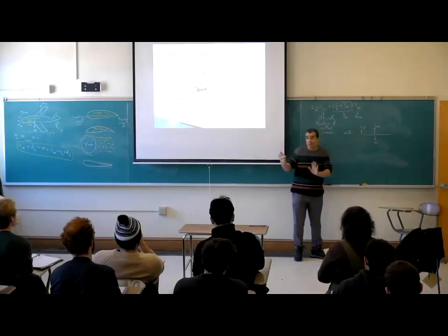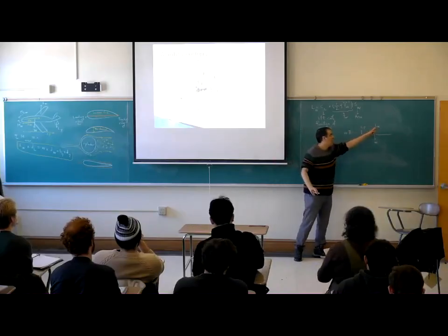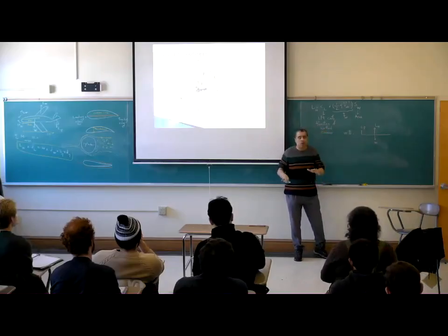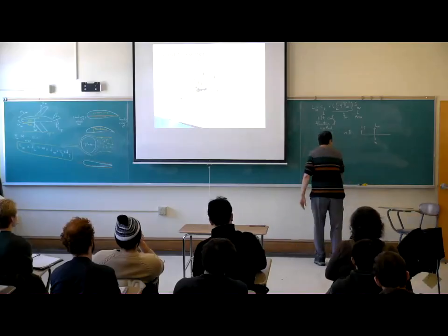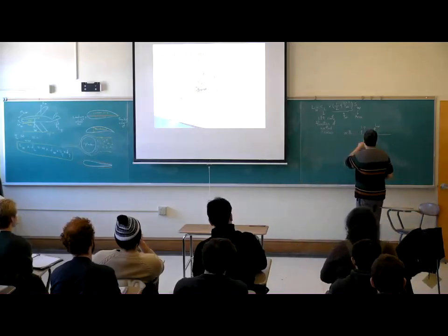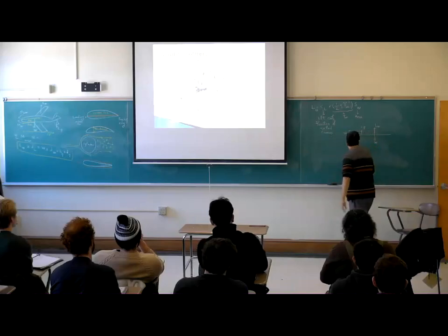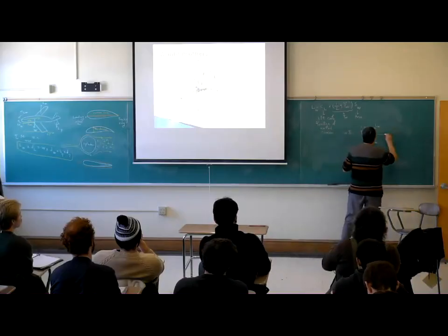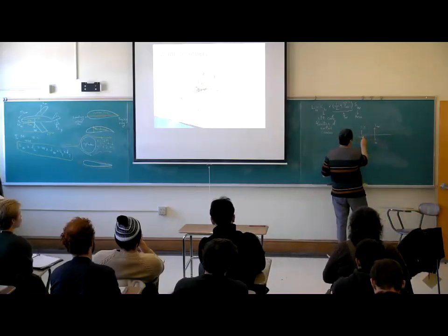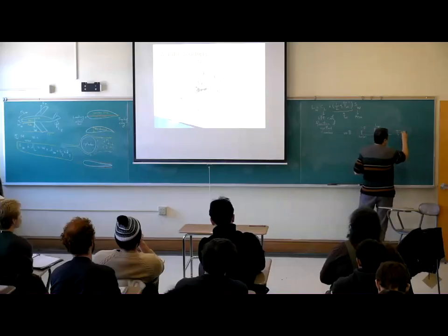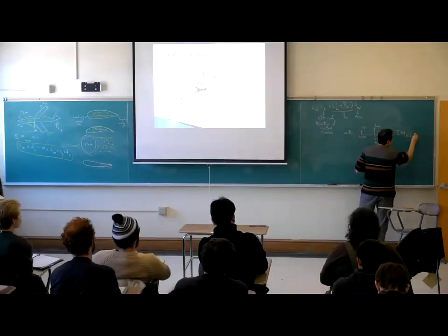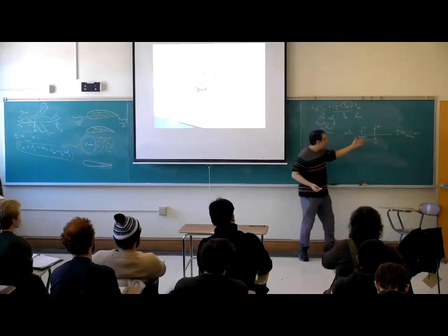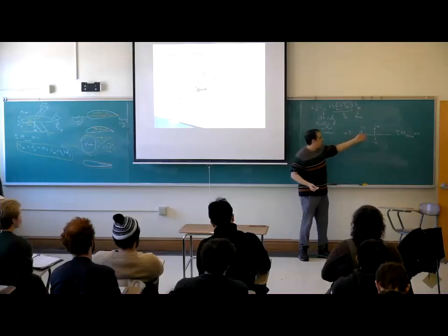I assumed the lift of the wing and weight are acting on the same point, which is not very correct. Yes, it is correct, because the moment on the leading edge is 0. Sigma M at the nose is 0. These two balance.